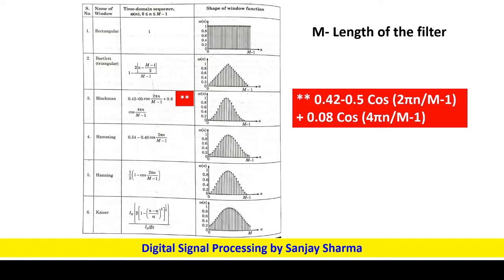Now, types of windows. There are several types of windows, and the first one is the rectangular window. It is just like a brick-like structure. And we have already discussed previously that when we have any brick-like structure, there would be the Gibbs phenomenon across the discontinuities. However, why do we still teach this? We teach this because it gives you the foundation of how to work with these filter numericals in a better way. So for the sake of understanding only we do it.